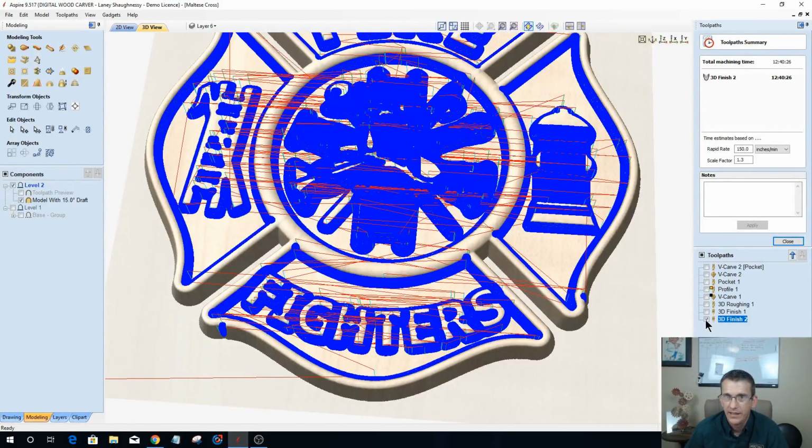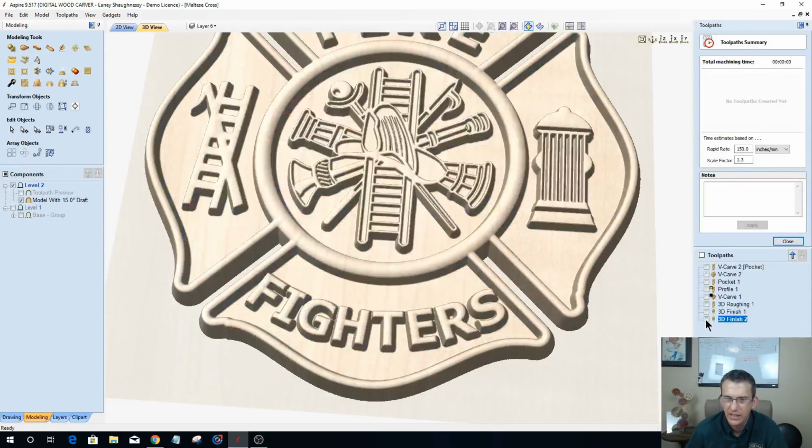So, right, my 32nd inch bit, based on my step overs and all that, just quadrupled the runtime. Okay. So I may not use rest machining. I may just carve the whole design with my 32nd inch bit, type of deal. But I could probably increase my step over or my feed rate and everything, because I am just coming back and doing cleanup. I could probably, instead of running 45, run a good 60 to 70 inches a minute, 75 inches a minute, and still get a nice clean cut, which would reduce time significantly.